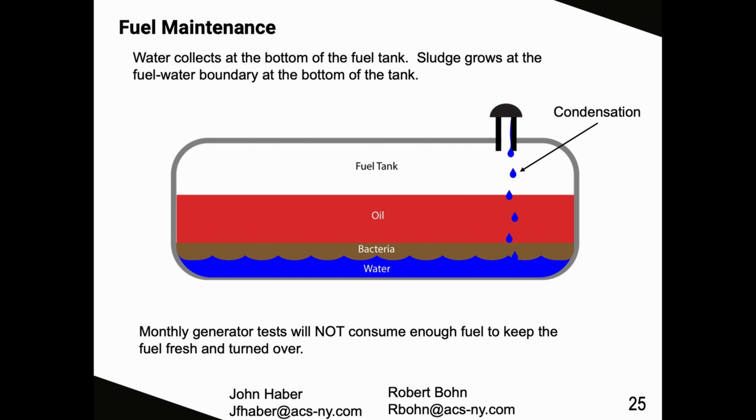This slide is a perfect representation of what we were talking about in the previous slide, just showing your fuel oil tank with your oil, your water, and again that bacteria layer that likes to grow in between. Any tank that is vented to atmosphere has the potential to grow this bacteria.